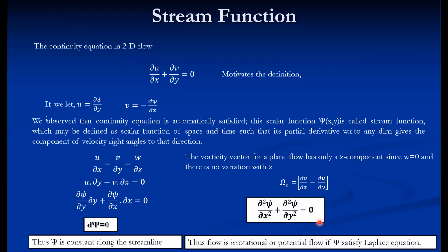In the case of velocity potential, we have already seen that if it doesn't satisfy the Laplace equation, then it is called an incorrect form of velocity potential. Because if the velocity potential doesn't satisfy the Laplace equation, then the flow is not possible. And if the flow is not possible, then there is no question of whether it is rotational or irrotational. That's why that φ function is an incorrect form of potential. So you have to memorize or understand these important characteristics for solving various numericals.